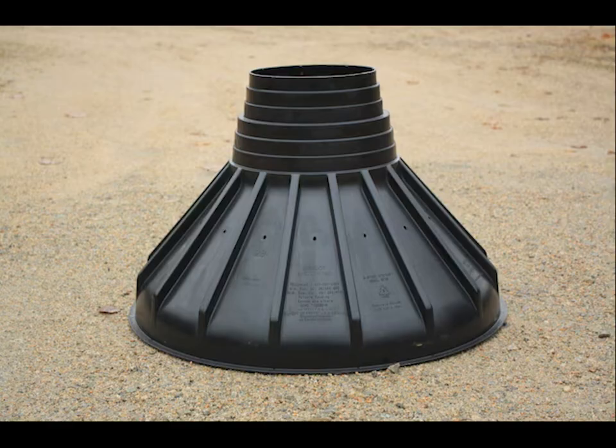The footers that I plan to use are known as Bigfoot footers. There is a link for them below. They have both a 20-inch diameter and a 24-inch diameter footer. Home Depot carries the 20-inch Bigfoot. The footers are to be bell-shaped, 12 inches thickness minimum.